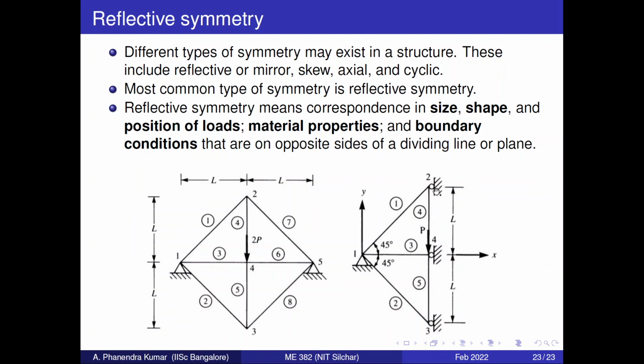When we have a roller support, we can have displacement in this direction, but the displacement in the perpendicular direction will be restrained. This is what we need to do after dividing the structure using the plane. We need to place the supports at the nodes through which the plane is passing, such that the displacement in the perpendicular direction at that node is equal to 0.